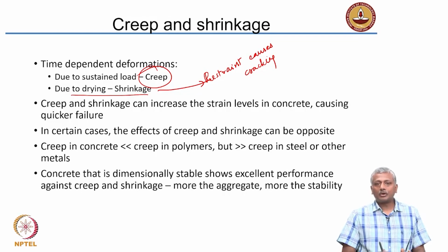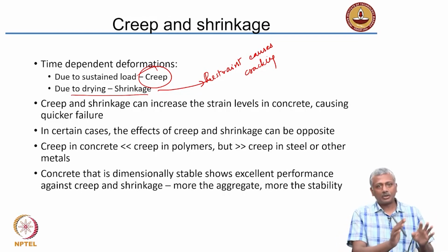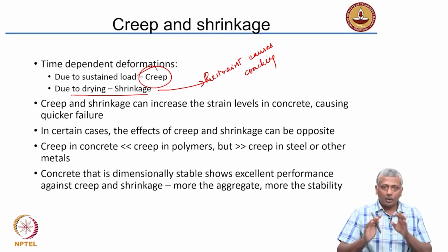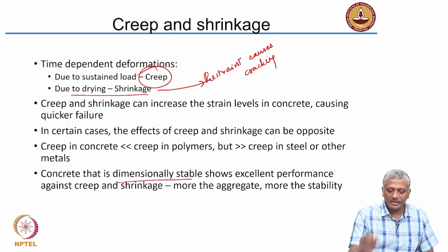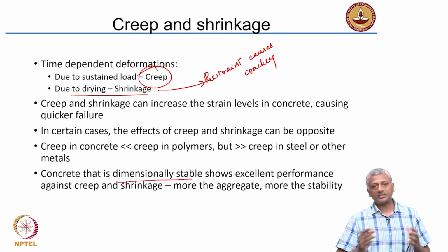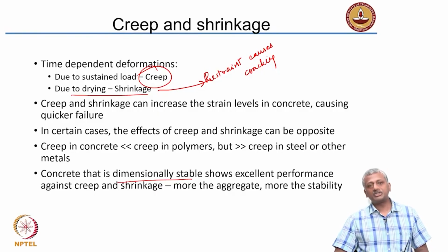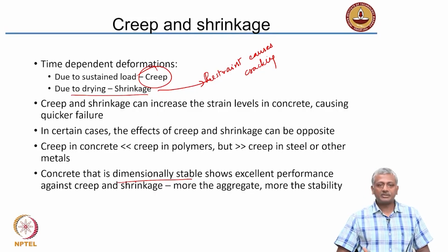So, you want your concrete to be strong, yes. You want your concrete to be durable. You also want your concrete to be dimensionally stable. That means it should not change its volume with time. And this time dependent change in volume is caused typically by creep and shrinkage.